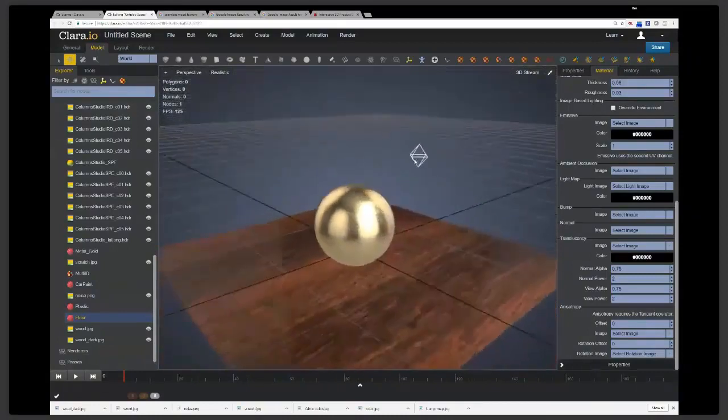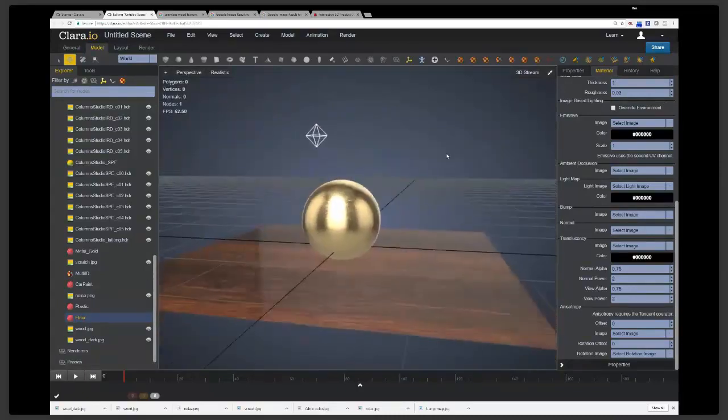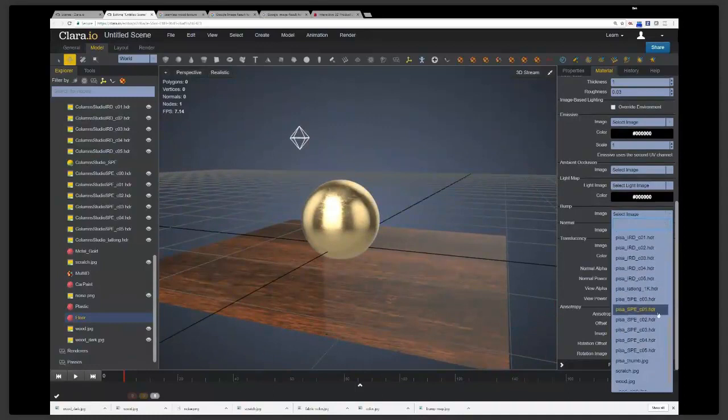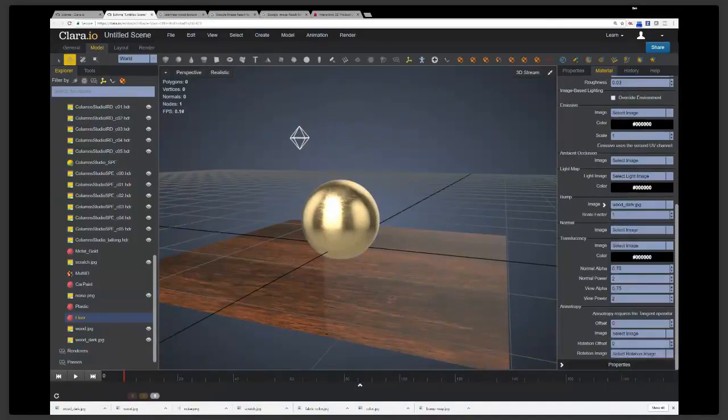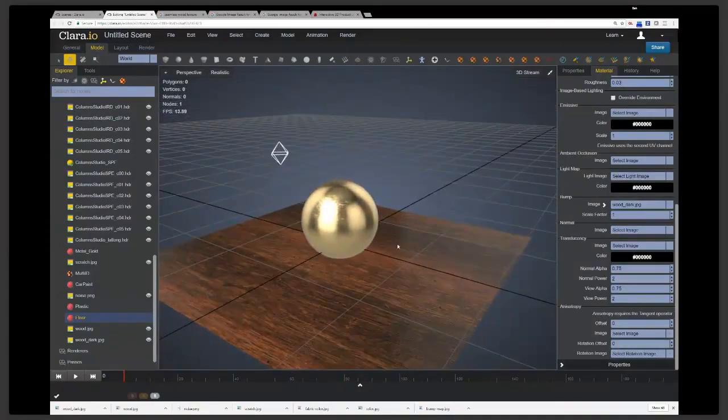And then you can see here I've got a really good clear coat on top of the underlying wood. You might want to put a slight bump, and I'd use the same underlying material. If it's expensive furniture, it's really not going to have a very strong bump, so I'd bring that down, because the clear coat really removes a lot of the imperfections in that material.